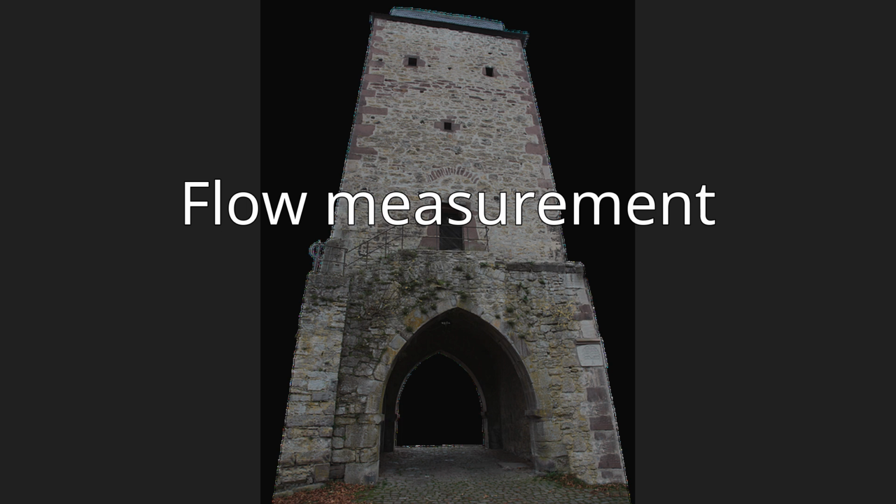Since the geometry of the top of the weir is known and all water flows over the weir, the depth of water behind the weir can be converted to a rate of flow. However, this can only be achieved in locations where all water flows over the top of the weir crest as opposed to around the sides or through conduits or sluices, and at locations where the water that flows over the crest is carried away from the structure. If these conditions are not met, it can make flow measurement complicated, inaccurate, or even impossible.